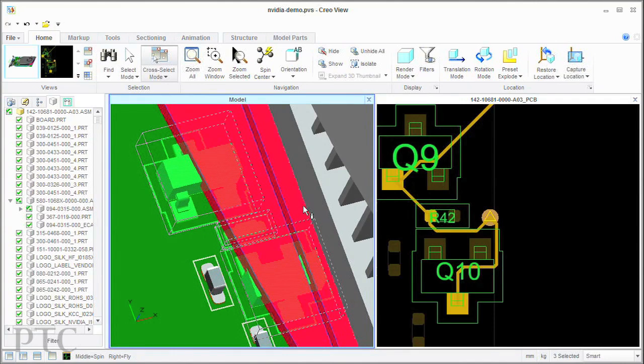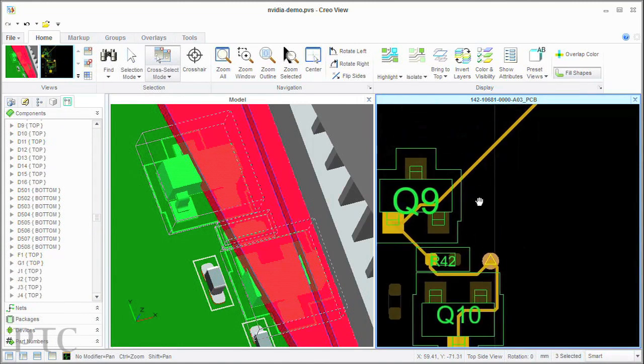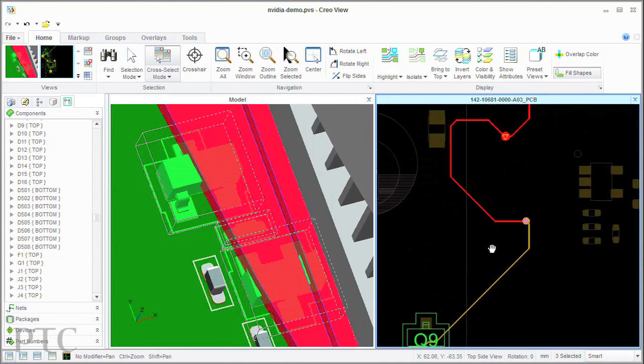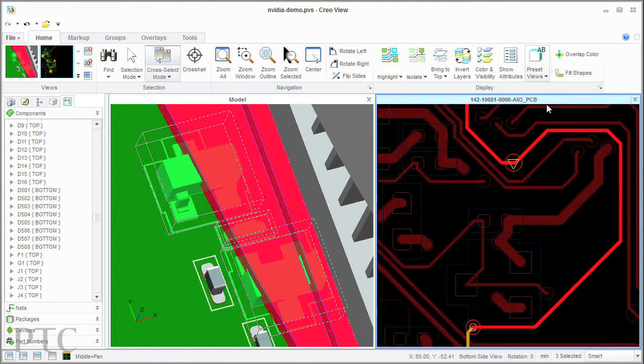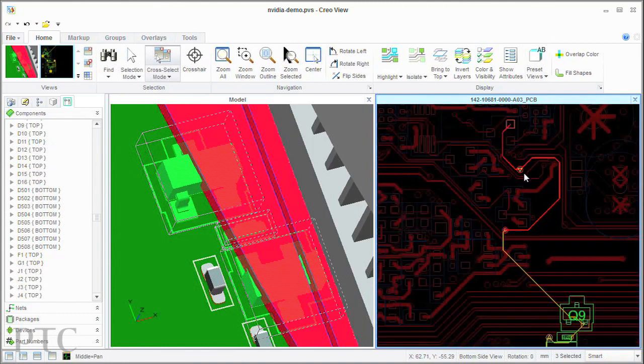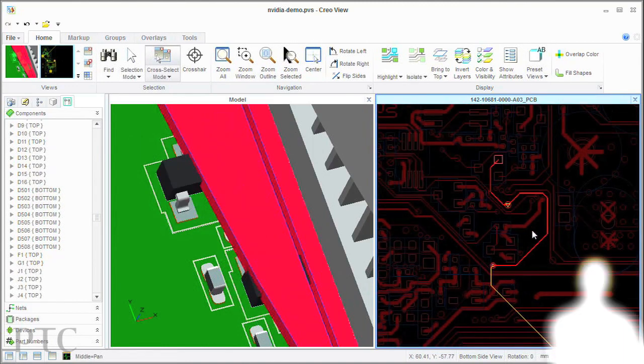So we go back to the layout and check whether there is another test point on this net that we could possibly use to get our test probe onto it. And sure enough, there's one right here on the bottom layer. So we flip the board around, so that we're looking at the bottom layer on the screen, just like we would have it on the test bench.